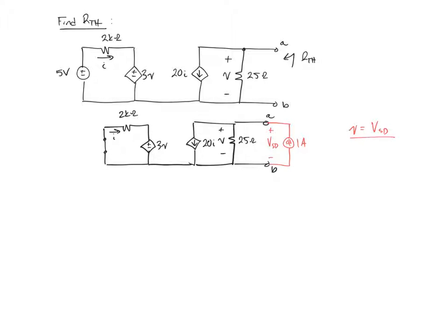So what are we looking at for the analysis? Well, we've got two essential nodes, so we can do this in one KCL equation, and we would require 1, 2, 3 meshes, although 2 of them are known, so we could do this in one mesh equation as well. I'm going to choose nodal analysis.